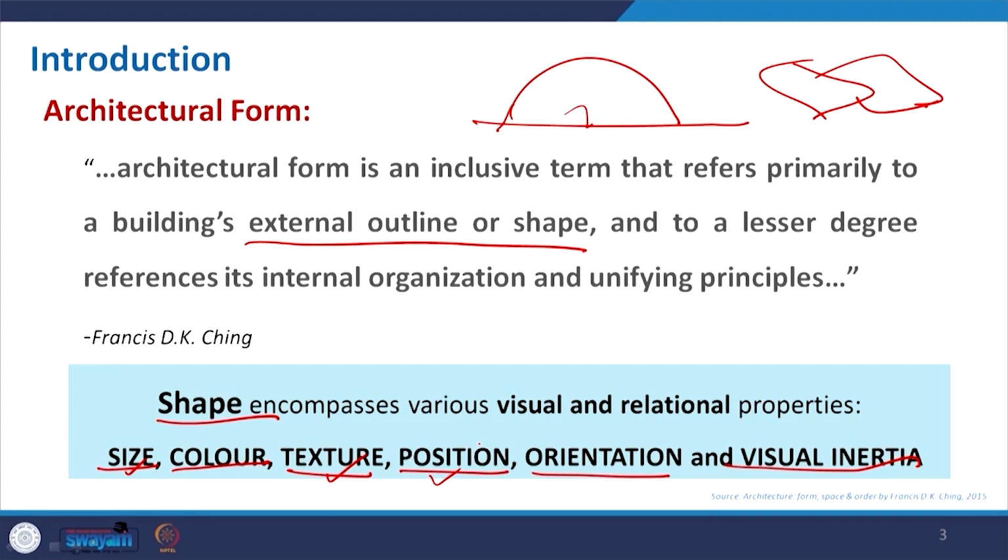If you recall the wind load that we have seen, when we place this rectilinear form and this is the prevailing wind direction, this creates thrust. In order to reduce that, if I rotate it a bit, we can minimize it. And visual inertia is very important, that will give a visual sense of stability.